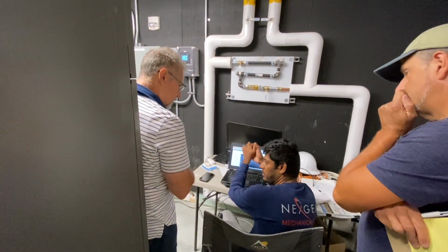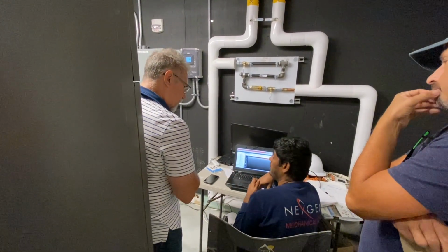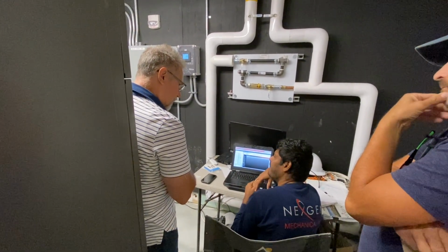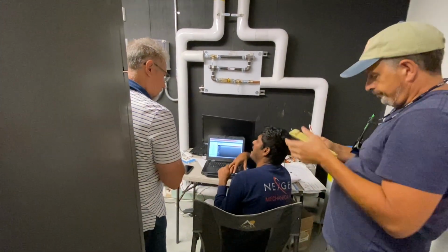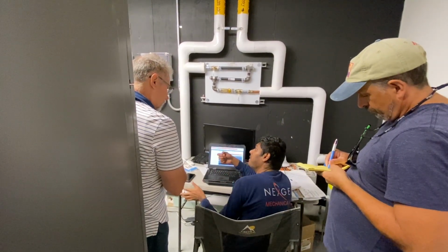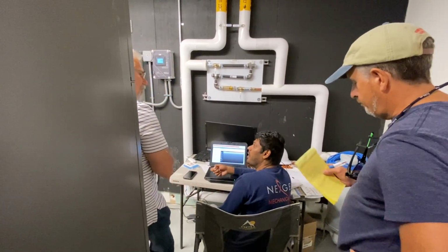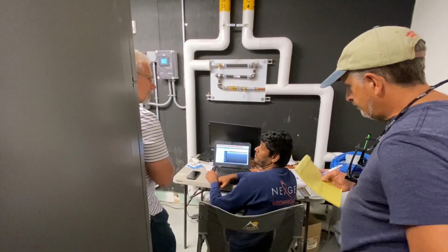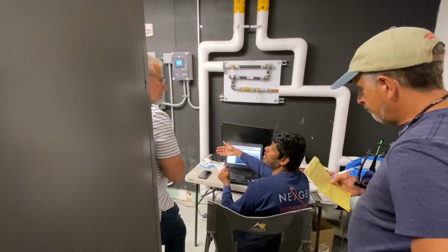But let's say no one is in that room. Now it goes to standby mode, because I think it waits for 15 or 20 minutes. After 20 minutes, it goes to standby mode. Now the standby cooling set point comes into the picture. Probably your standby cooling set point is not 74, because 74 is an occupied set point. I want to give 2 degrees more than the occupied set point.